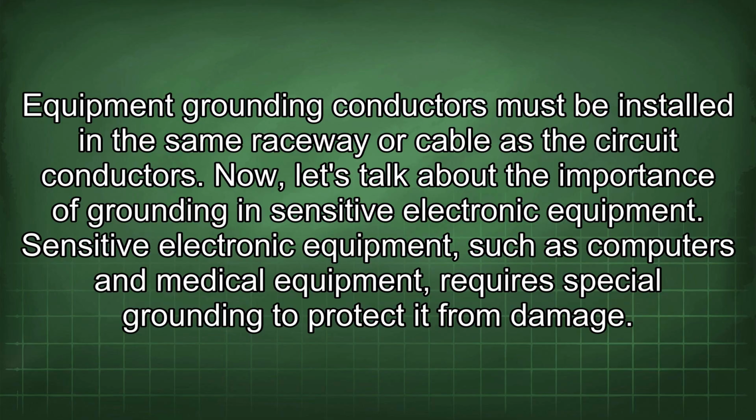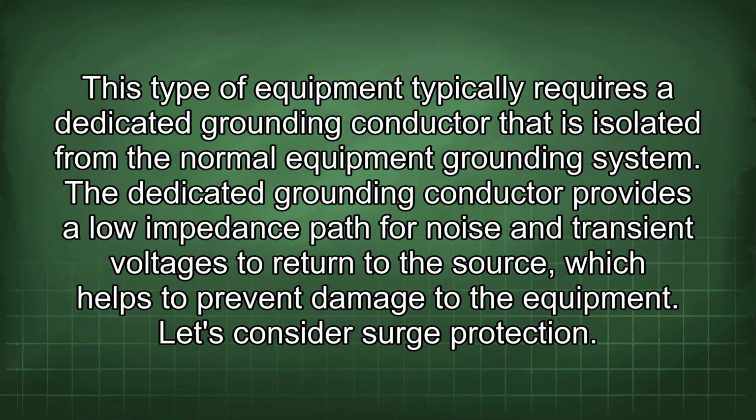Now let's talk about the importance of grounding in sensitive electronic equipment. Sensitive electronic equipment, such as computers and medical equipment, requires special grounding to protect it from damage. This type of equipment typically requires a dedicated grounding conductor that is isolated from the normal equipment grounding system.